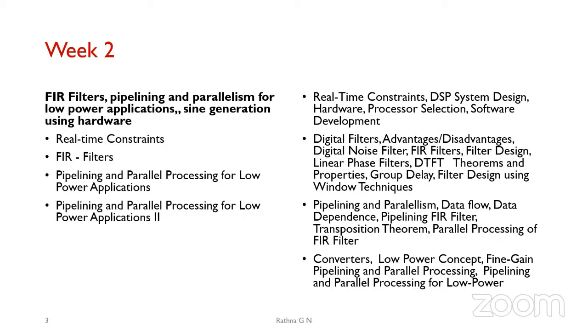One of the things is the design part of it, or getting the coefficients. We do it from MATLAB, and then we'll be using those coefficients in our DSP processor, and then we'll be running our code. Filters are usually used in applications of modifying the input signal, or when you want to eliminate certain frequencies.